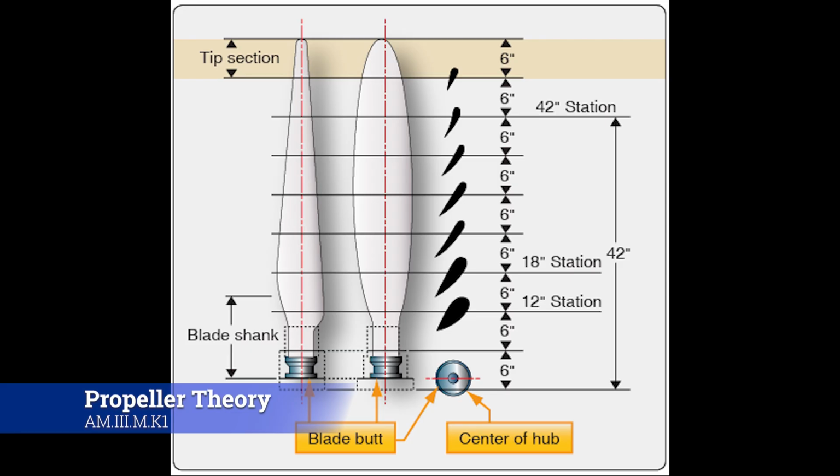Now, depending on the type of propeller, you might need to be really specific. Like if you're on a J model of a C-130 and it's on the number 3 engine, and you look at that blade, there's 4 blades on it, you can't just say the engine blade has been damaged. You're going to have to say, okay, it's on engine number 4, on blade such and such, with a serial number for that blade, at this station, there's this damage. You have to be really precise with it, especially in bigger, more complex operations where there are a lot more people.